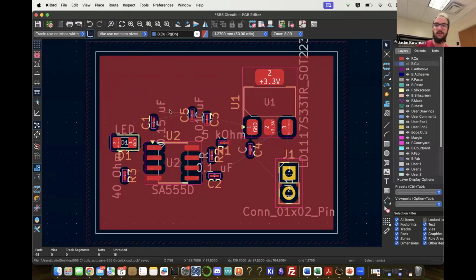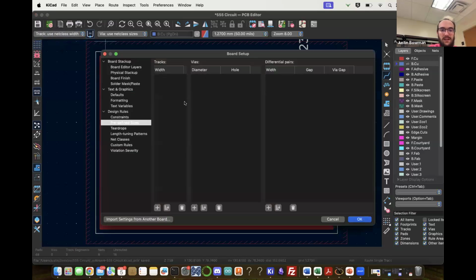So now that we have all of our layers defined, if we go to route tracks, we can start connecting stuff. In order to change widths, like Hasith was talking about, we go to the top left and we can edit the predefined sizes.